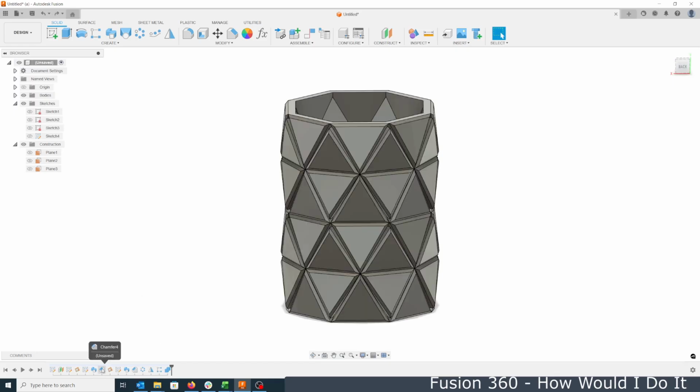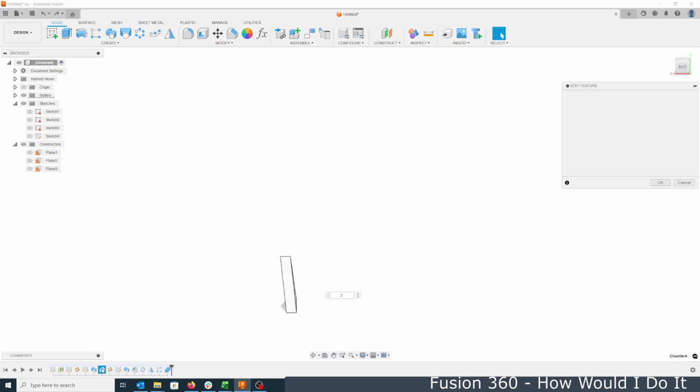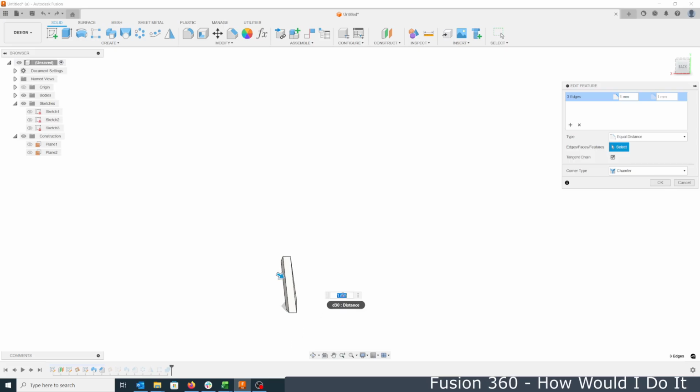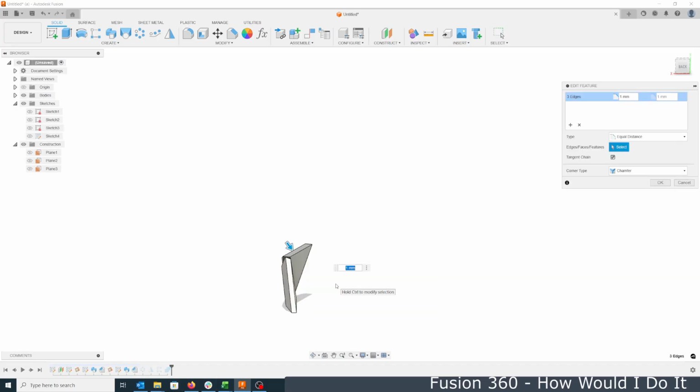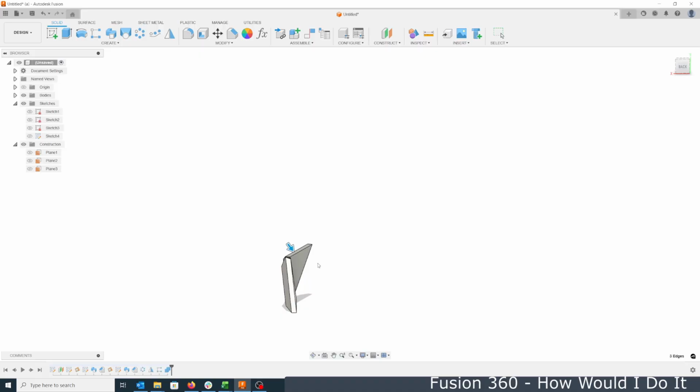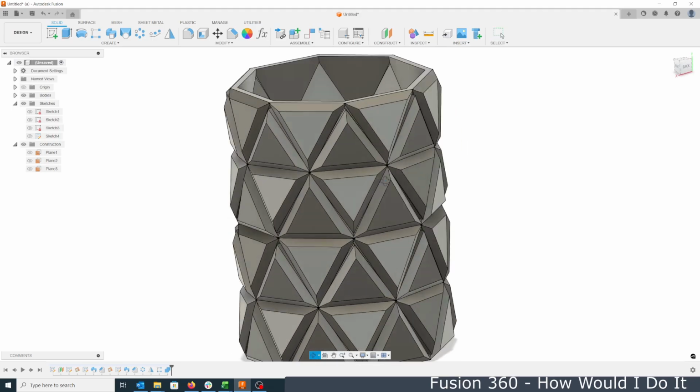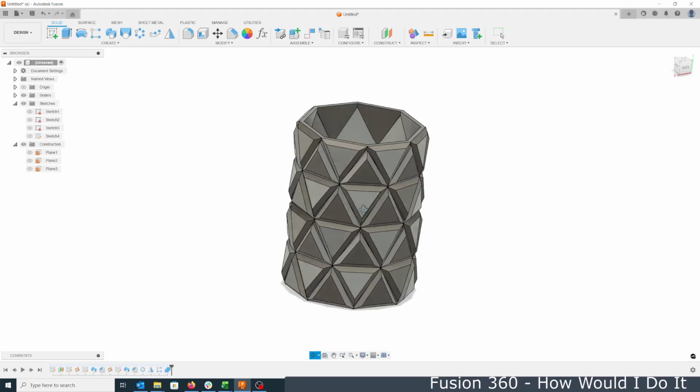If we edit these chamfers, this chamfer is D30. Well, if we say here 2 millimeters and say here instead of 1 we type D30, we will have also 2 millimeters, and we will see how it looks.